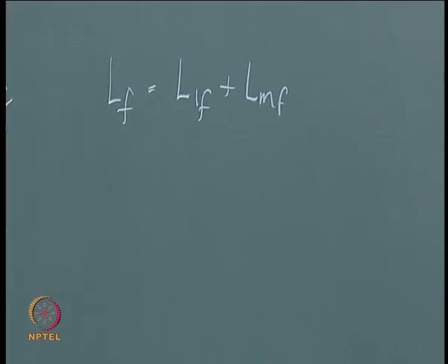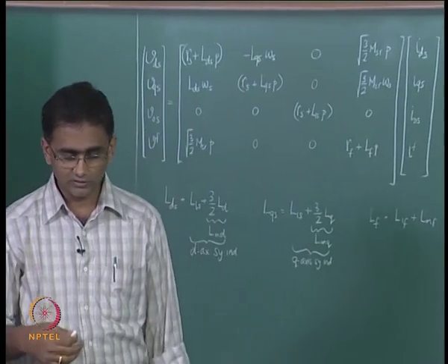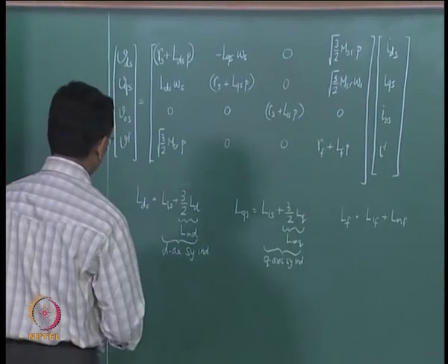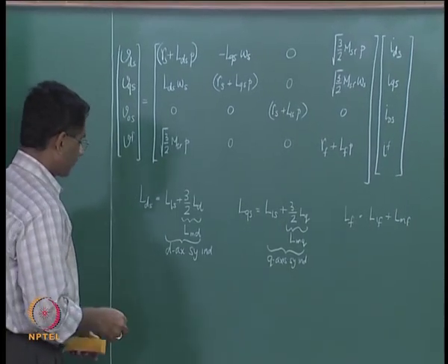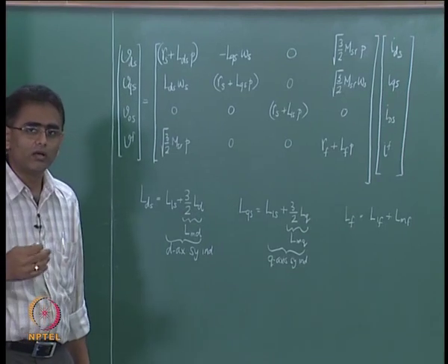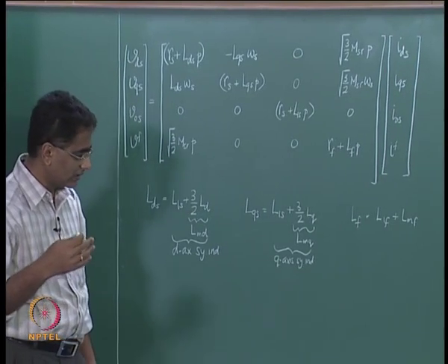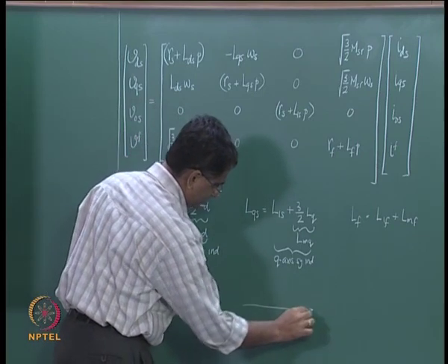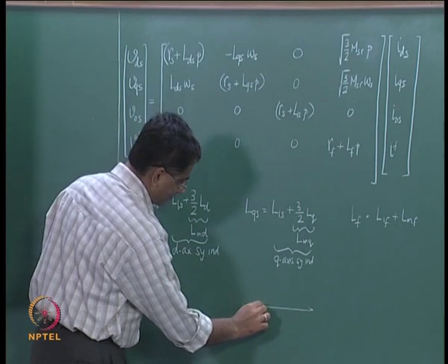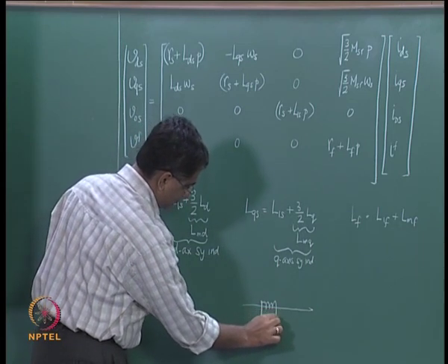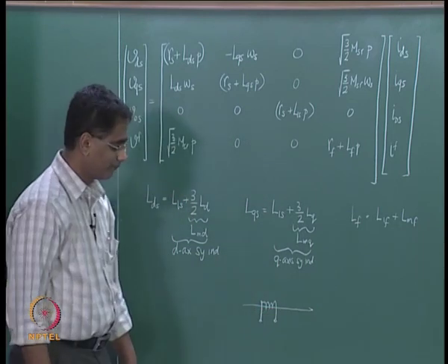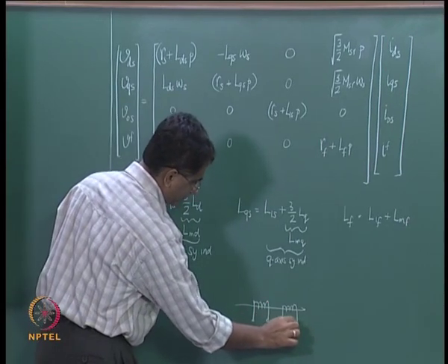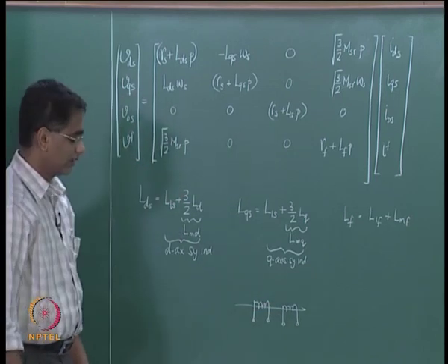Now we started in the last lecture to refer the rotor variables to the stator turns, and when we do that we said that it is referred to the stator turns under the assumption that if you look at the d axis, it has the field coil, which is on the rotor, and then it has a fictitious coil derived from the stator, that is the ds coil.